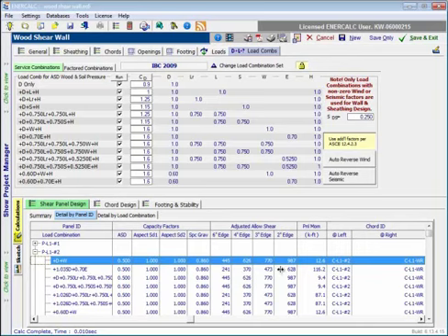So embedded behind these values is both calculation and logic to determine how to treat the values of resistance from side 1, the main side, and potentially a side 2 for the particular load combination that's referenced over here at the left. A lot of information is going on behind these values, a lot of work and a lot of logic taking place to report the controlling value that you need to compare your applied unit shear to in order to come up with a required fastener spacing.